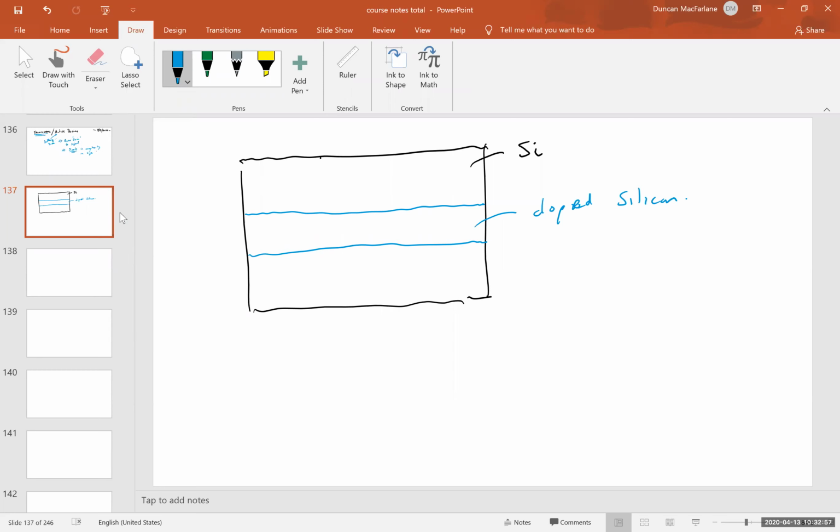So the way I'm going to do that is I'm going to put that lacquer or photoresist across this entire area. I'm going to mask out this piece and this piece and etch away the lacquer or the photoresist. And then I'm going to bombard this with ions. And then I'm going to heat it to pull the ions into what's called a channel.